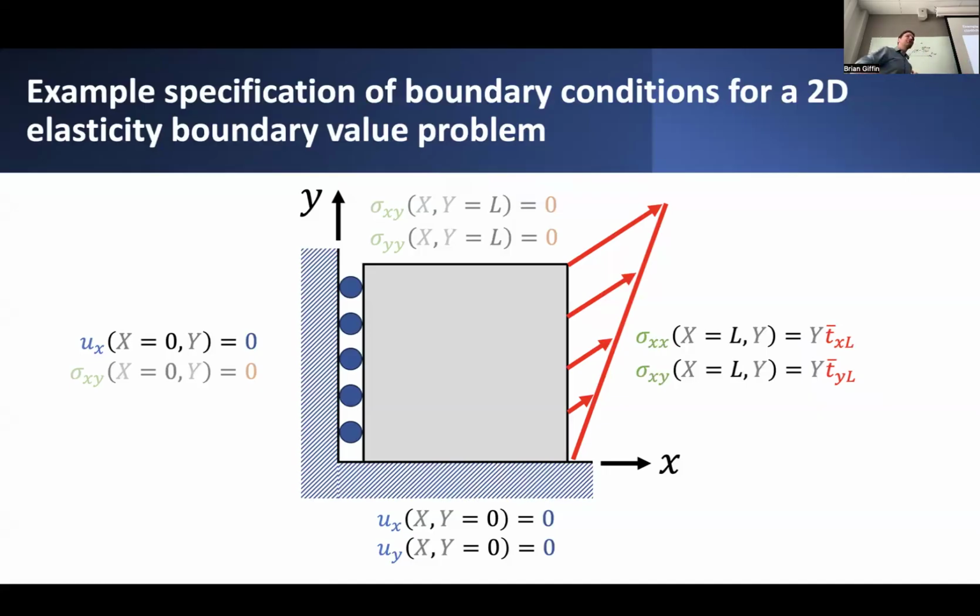But if we're not prescribing displacement in the y direction, we actually have to supplement this boundary condition with some additional statement that the shear stress exposed on this surface has to be equal to 0. That's equivalent to saying that there's really no way for us to resist the sliding. And if that's the case, then truly there is no shear stress that should develop on that surface. If it's allowed to slide, there are no transverse shear stresses that could develop.